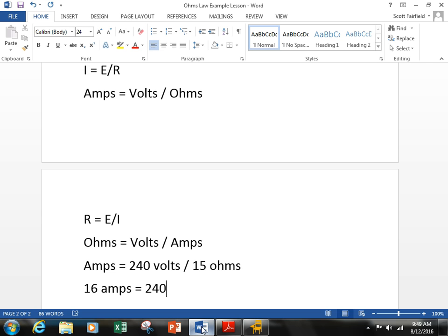So you want to make sure you've got an electrical wire that can handle 16 amps, and usually electricians will plan for something above that. Let's say 20 amps, because most of your circuit breakers you'll see are 15 amps, 20 amps, and they'll go from 20 to 30 amps, and they'll make sure they have a little built-in cushion that the wire and the breaker can handle.